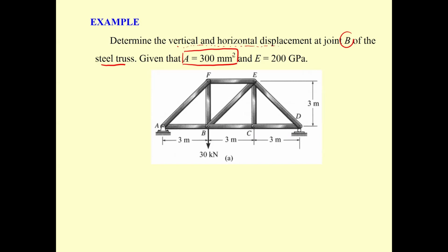Okay, this is supposed to be easier. And the steel has a modulus of elasticity of 200 gigapascals. Then, due to the force of 30 kilonewtons, the bottom portion is going to be in tension and the top portion is going to be in compression. Then tension produces what? Elongation. So I believe we are going to put downward over here and have a horizontal displacement like this one.